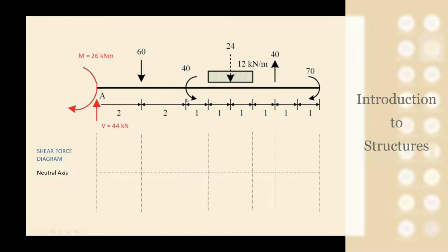We can ignore this moment because the shear force diagram is not affected by the moments at all. An important point where we're going to see changes is the initial point of the UDL and the final point of the UDL. Again, this punctual load, and of course the end of the beam is an important point as the beginning of the beam, because they are the points where you close the diagram, we say.